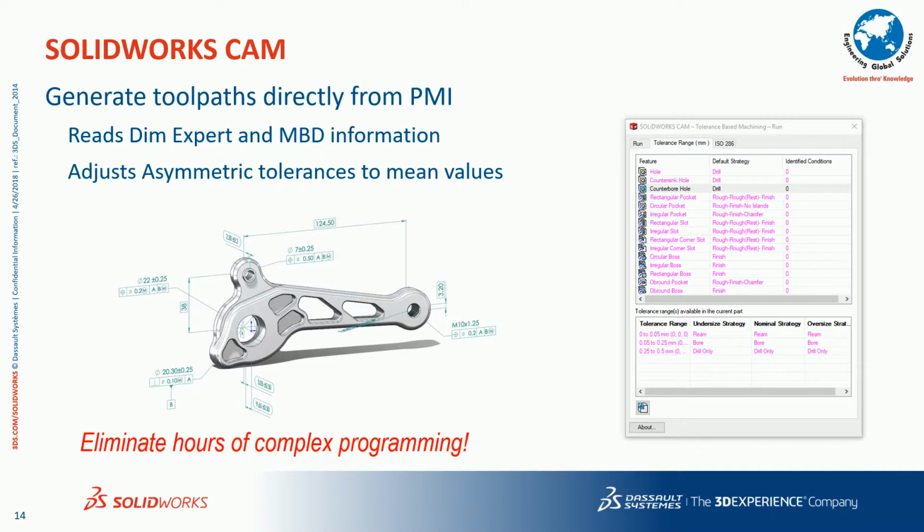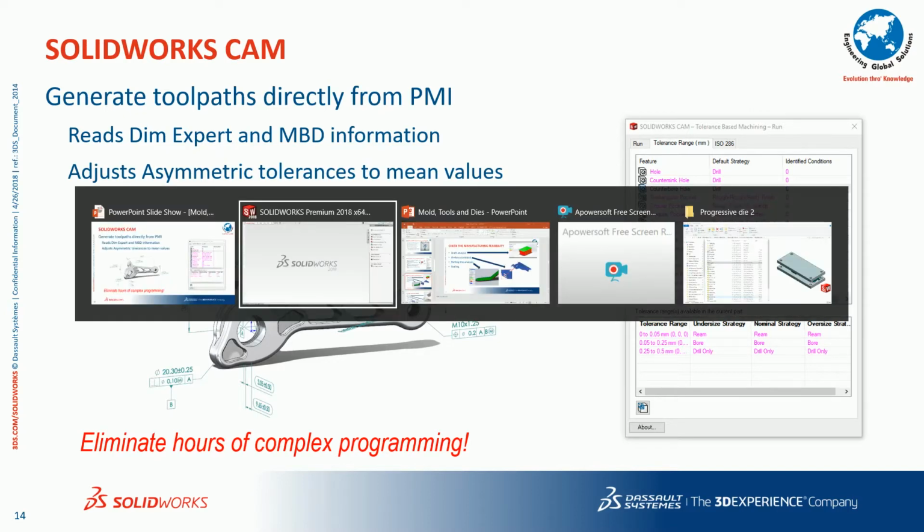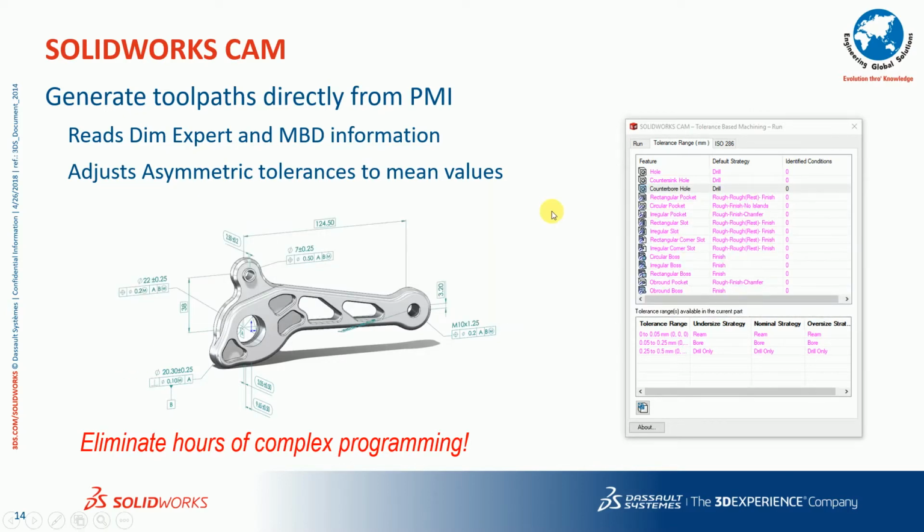And again, if you are making the same operation for some other component, knowledge based machining will give you all the information you previously used. So again, you don't need to spend time on all this set of information every time. And if you are providing the product manufacturing information like tolerance, the reference datums, and the hole sizes, everything in your 3D annotations, it also has the capability to capture all that information inside the CAM. So let me quickly get into the software.